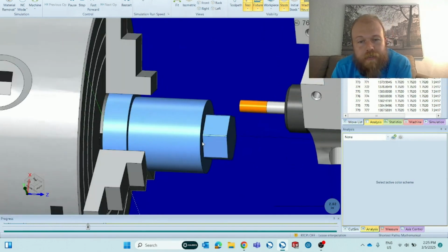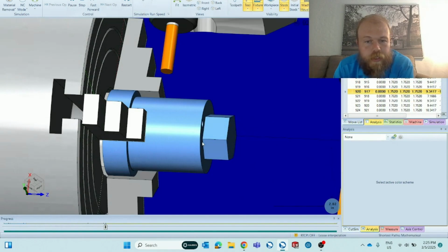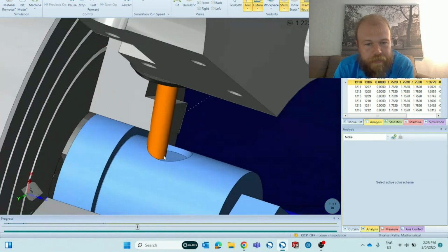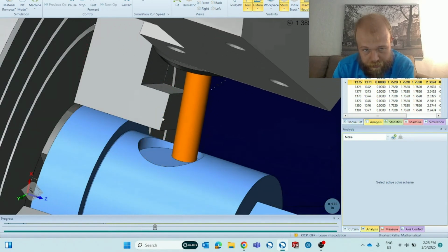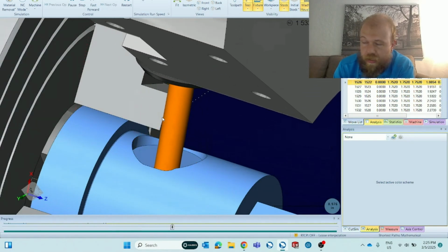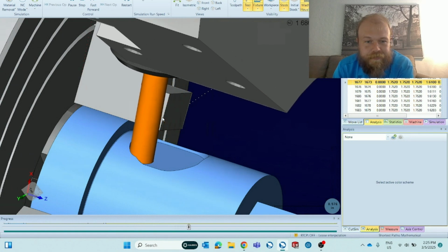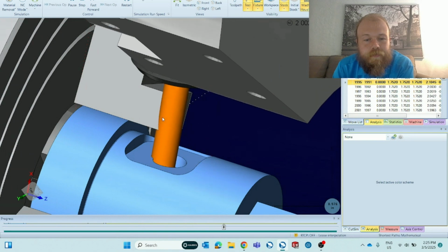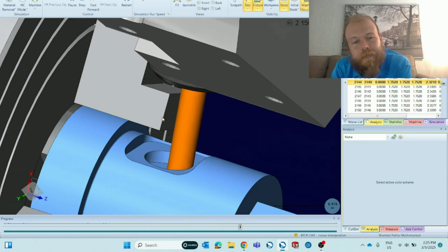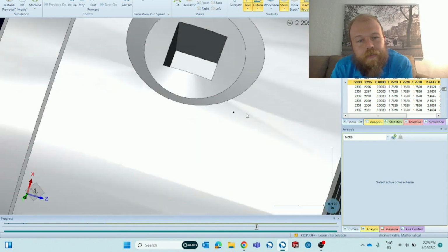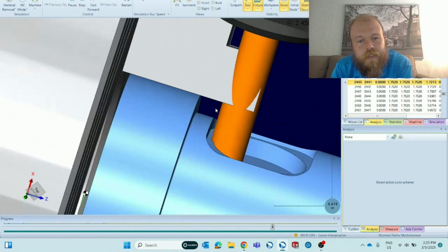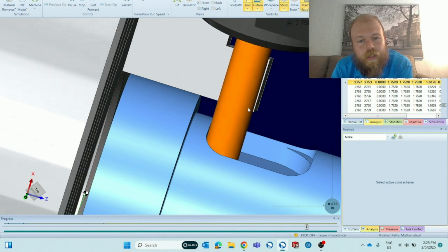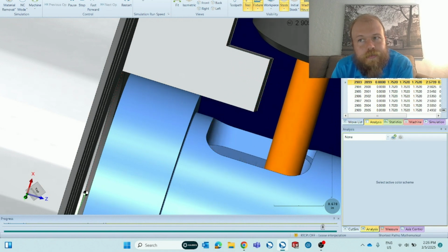We've got the profile rough, the profile finish, the drill of the 2 holes, and then it comes in on the side. Tries to pocket and profile finish on the side here, but it's running into the jaws, and it'll cut all of that out. But yeah, this is a good thing for simulation to see. If we want to make sure everything looks good, we want to move it out. Let's see, that's at least a 1/2 inch because of the tool. So we'll go another inch.